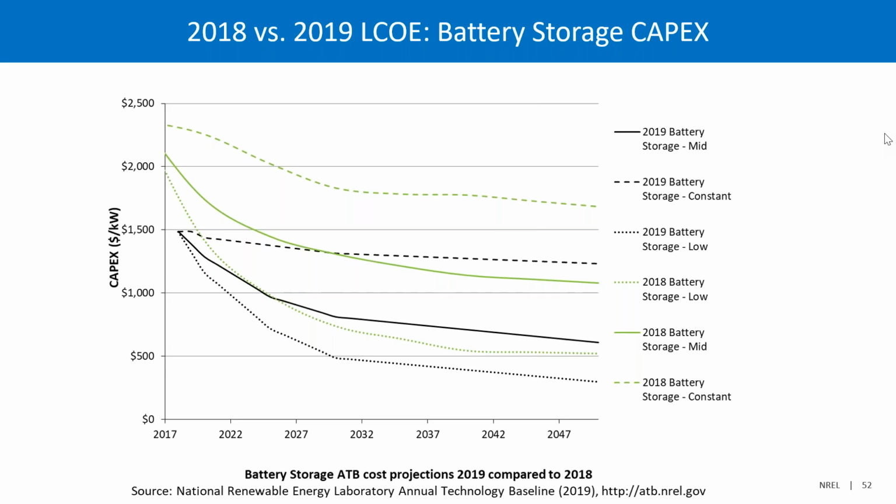So I believe that our ILR for utility scale is 1.3, and in cases where we needed to convert for AC, it is 1.15, but that really wouldn't come up unless we were converting some sort of projection where we needed to make that conversion.